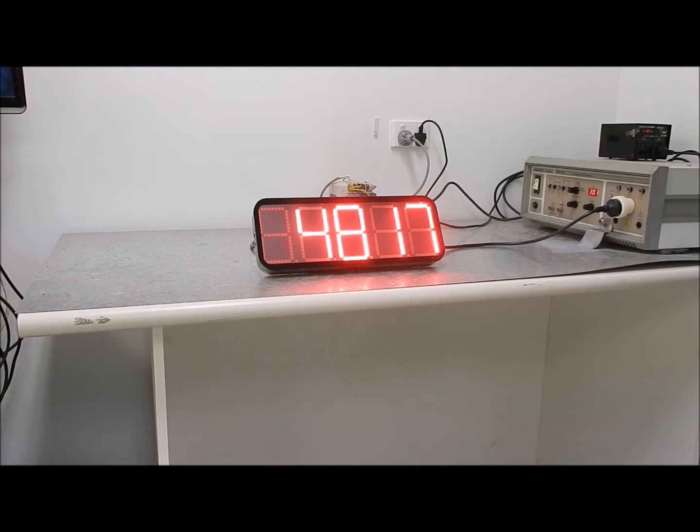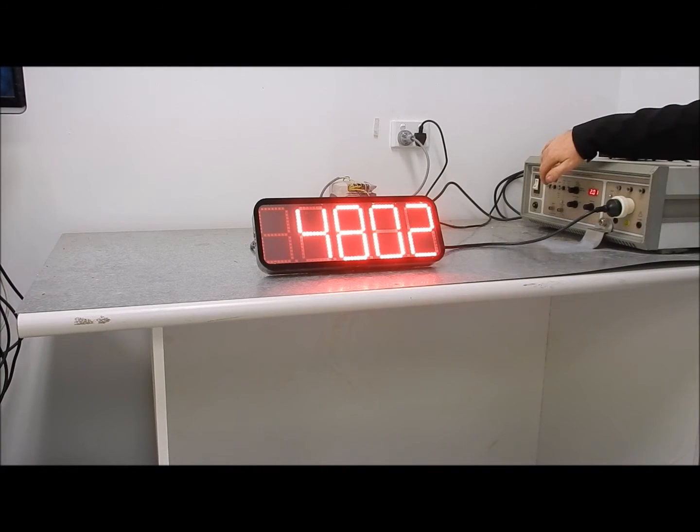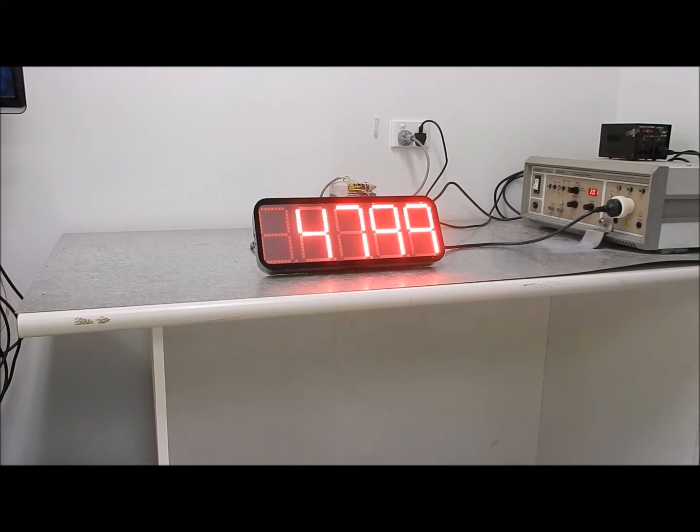So what we're going to do now is generate a couple of kilovolt pulse into the display and watch what happens when we push the button to send that spike down the line. Boom! The display corrupted, just briefly, and it recovered. So if you see a display glitch when you hoist or when you long or cross travel, it's a pretty good indication that there's an electrical noise problem, or electrical noise being generated at that point.